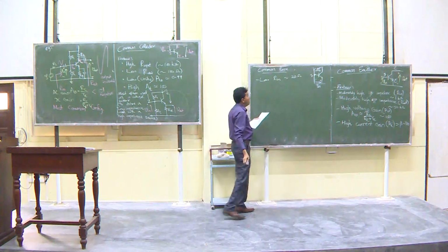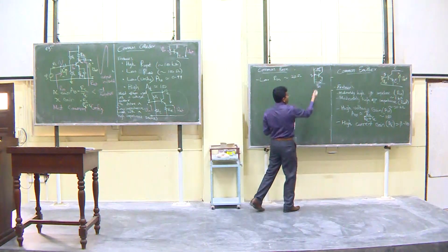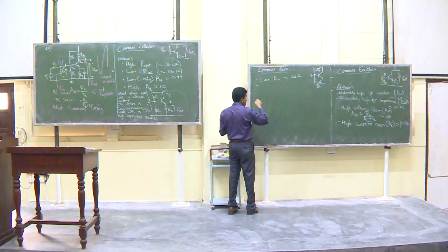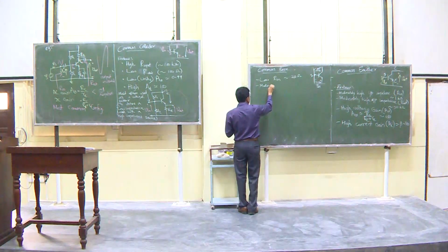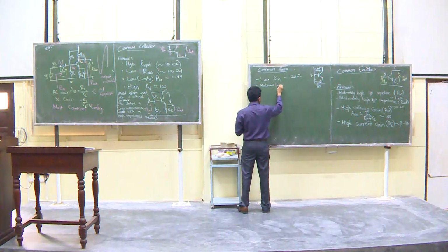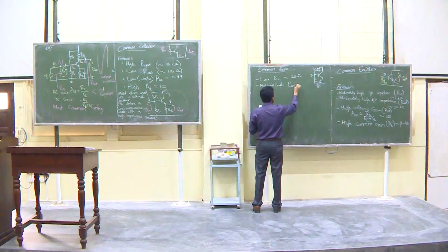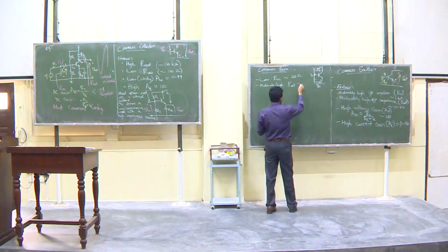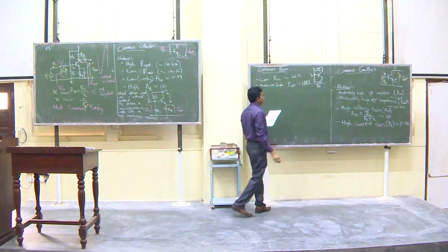So very low input impedance because of the forward biased diode. Moderately high output impedance, in the range of a few mega ohms, maybe 1 mega ohm or 1 to 2 mega ohms or something like that.